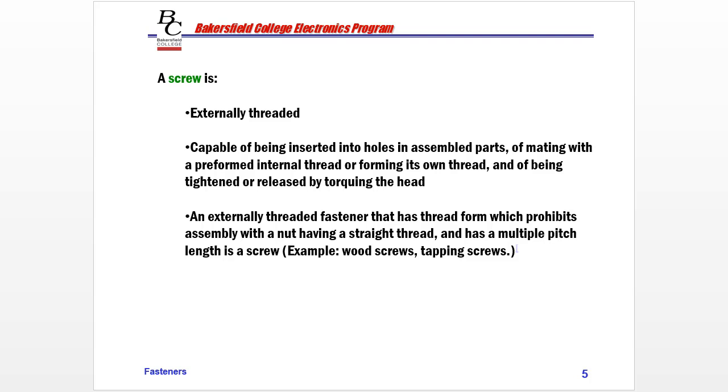An externally threaded fastener that has a thread form which prohibits assembly with a nut having a straight thread, and has multiple pitch lengths, is a screw. So wood screws, tapping screws. A nut would not go on a screw is what that is saying.